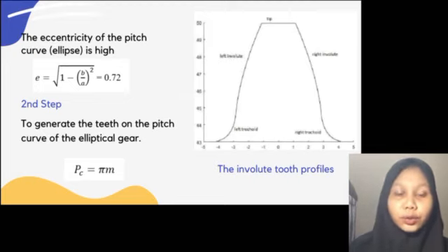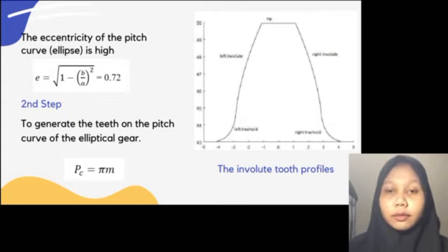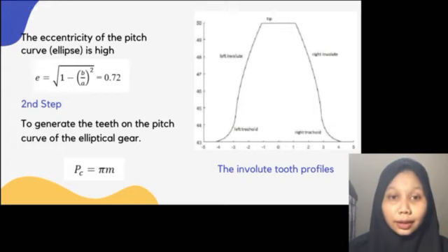This figure shows the output of the created function for the input rho equal to 47 mm, m equal to 3 millimeters and phi equal to 2 degrees. Combining all the previous MATLAB functions and scripts together gives a full software code to generate a second order elliptical gear.